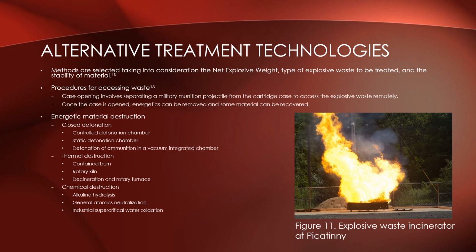Thermal destruction is a closed burning or incineration technique that captures off-gases and treats by filtration and scrubbing. One example is a rotary kiln, which gets equipped with a discharge system, afterburner, air pollution control system, and automated control system to move munitions forward and isolate feeds from propagating explosions, ensuring complete combustion of the energetic waste.